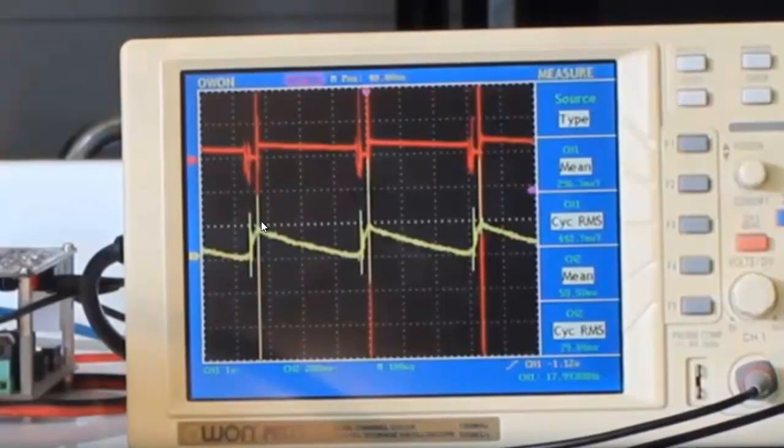Remembering these traces here are measuring current. I think that one's the light, and I think this one here is the other circuit, the diode coil. So these are 2 separate coils, 2 separate waveforms, but they do match up. You can see that there's an on time and this is an off time, and if you look very closely, it's the graticule line there, so anything above, there is a ramp down. You can see this is ramping down as well, ever so slightly.